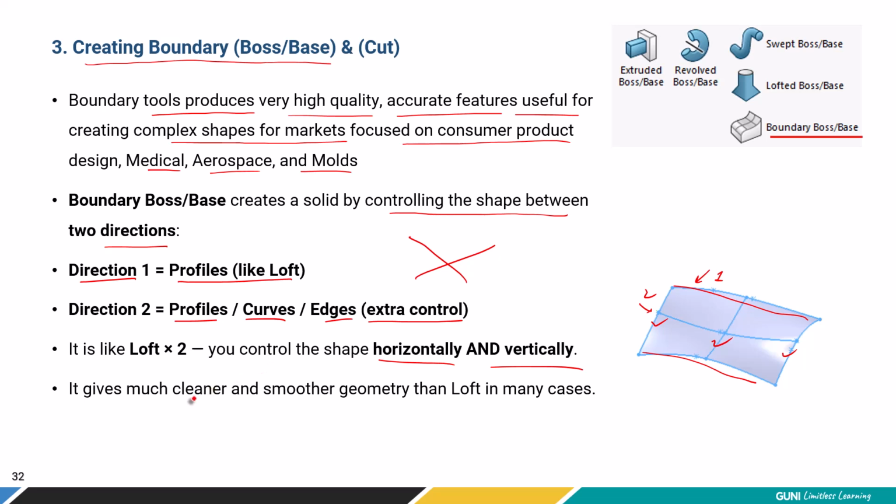Now it gives much cleaner and smoother geometry than loft in many cases. Sometimes users have a confusion about what to use, either loft or boundary. Remember, if you are in the business of creating consumer products where the outer surfaces are very important and critical, then try loft first. If you are able to achieve the result you desire, then it's okay. If not, then try the boundary boss base.